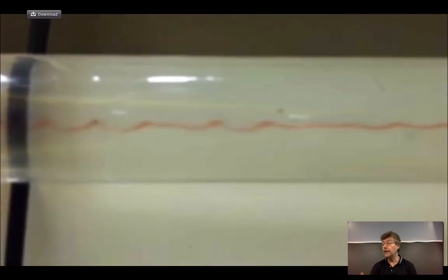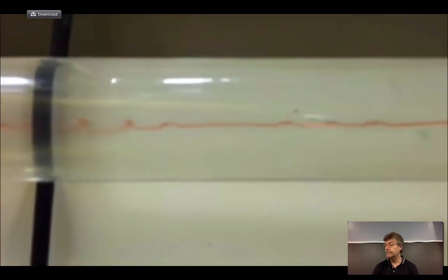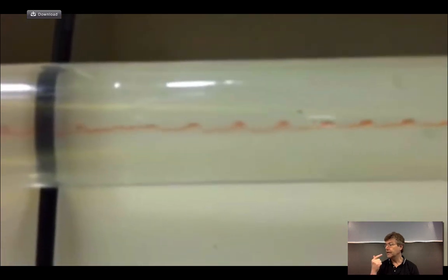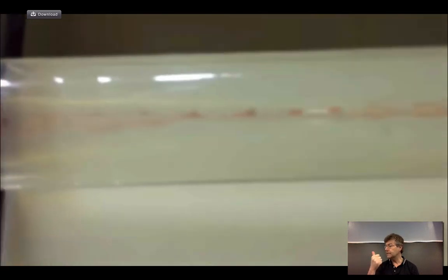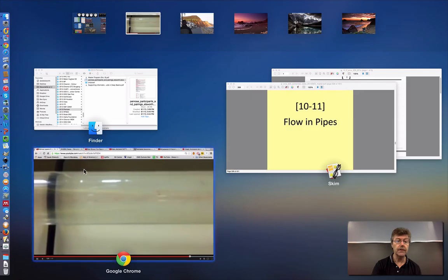So those are the three requirements that we have: geometric, kinematic, and dynamic similitude, which are embodied in ratios of the length dimensions, including the roughness, the Reynolds number for kinematic similitude, and Euler number similarity in terms of the pressures we have to apply upstream to drive flow. And so that's essentially what we would like to look at.